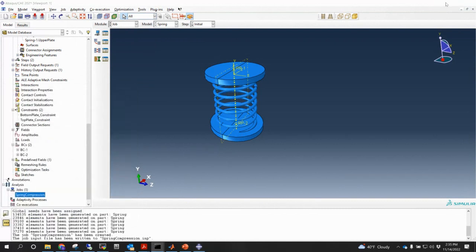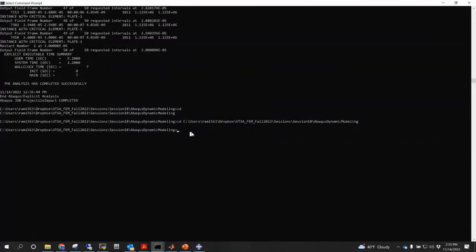This computer doesn't allow me to do that. I don't know why. So the way that I run from the command line is abaqus job spring compression, cpus 16, interactive, which just shows me everything on the screen. And if I have a job with the same name, don't ask me to delete it or not. Just go ahead and rewrite everything. So let's kill the computer.